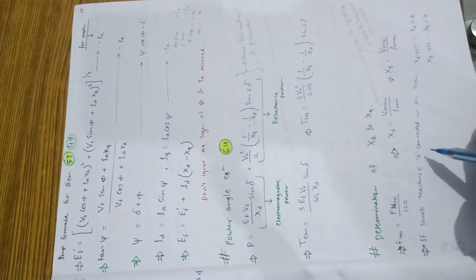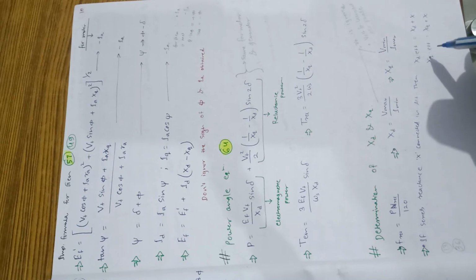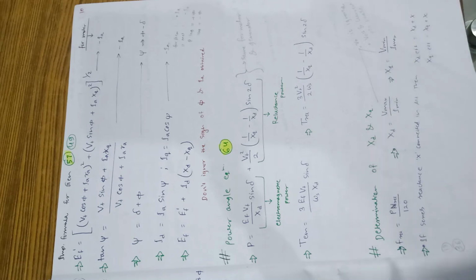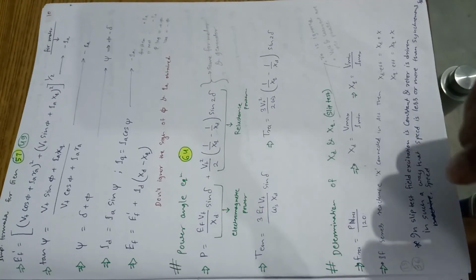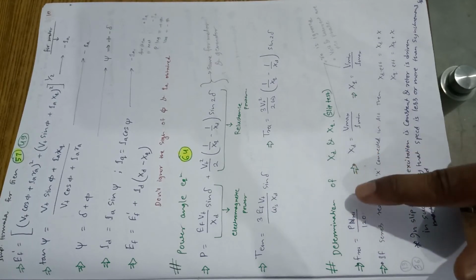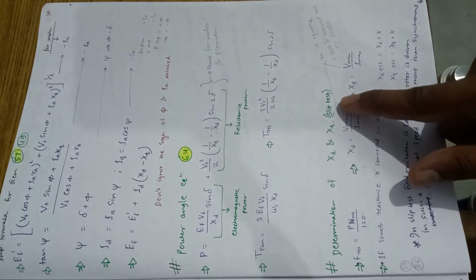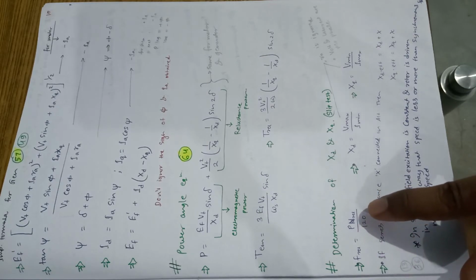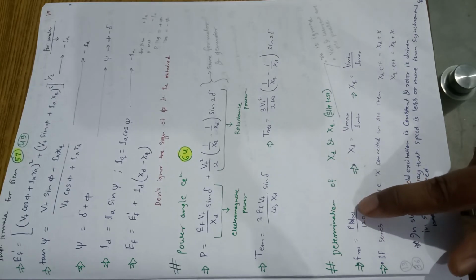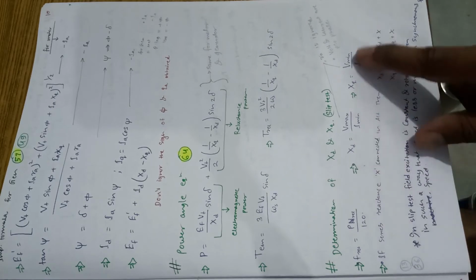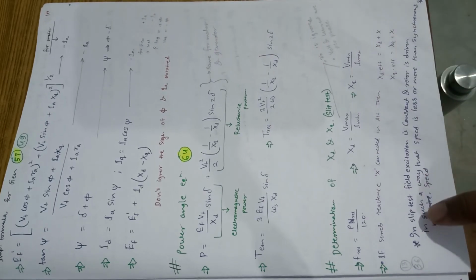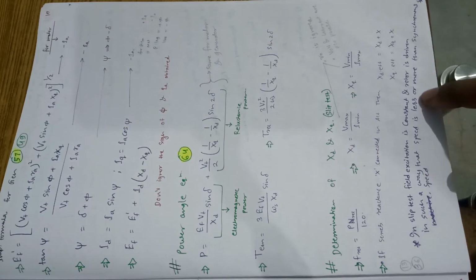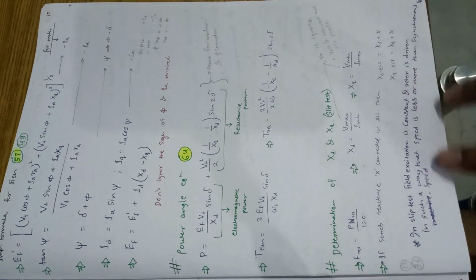Okay, if series reactance X is connected in the alternator, then overall xd effective will be xd plus X, and xq effective will be xq plus X. Okay, that's all. Few points were left in determination of xd and xq, that is also known as slip test. Frequency in rotor equals to P N relative upon 120, and this we have already discussed. In the slip test field excitation is constant and the rotor is driven in such a way that speed is less than or more than the synchronous speed. This is only in the slip test we do.